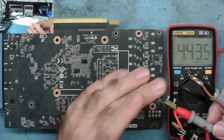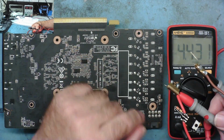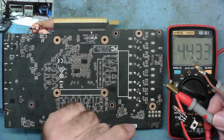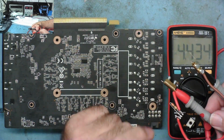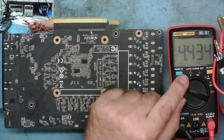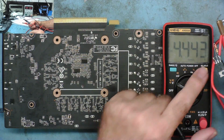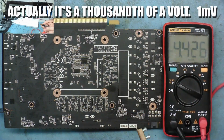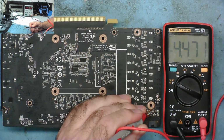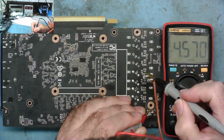So I've now reconstructed my short circuit finder. Let's see if this is actually sensitive enough to determine which of these four phases has the short circuit high side MOSFET. This is set to volts range, and you need a multimeter that is quite sensitive, so this reads down to 1/100th of a volt. We're now going to connect the positives to the 12 volts coming in. Then I'm going to try on each of these coils to see what reading I get.